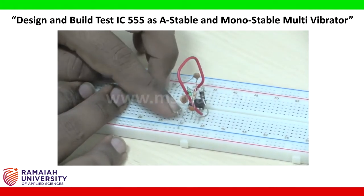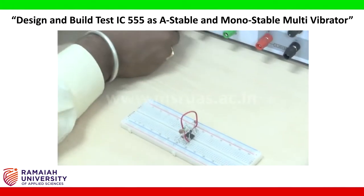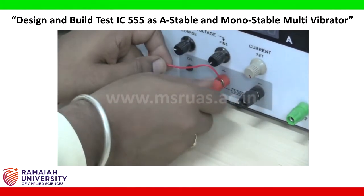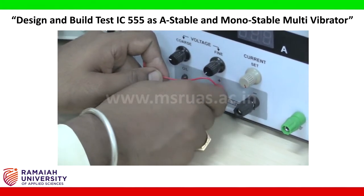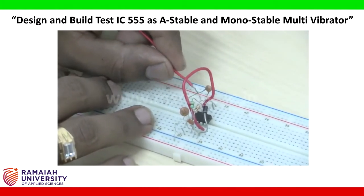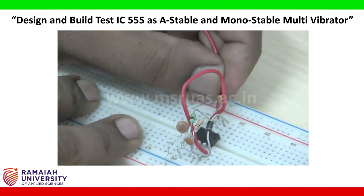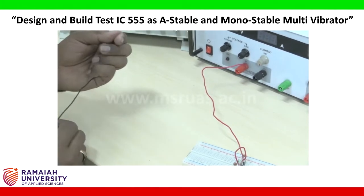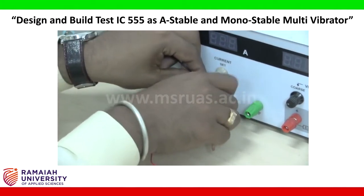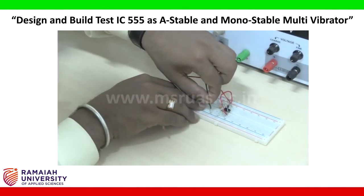This is ground. Now I am taking the connecting wires to connect the DC regulated power supply. The positive of the DC regulated power supply will be given to pin number 4 or 8. Now I am giving this to pin number 4. This is pin number 4. I am giving somewhere here. Next the negative I am going to connect to ground. Negative I connected to ground. This is the ground.